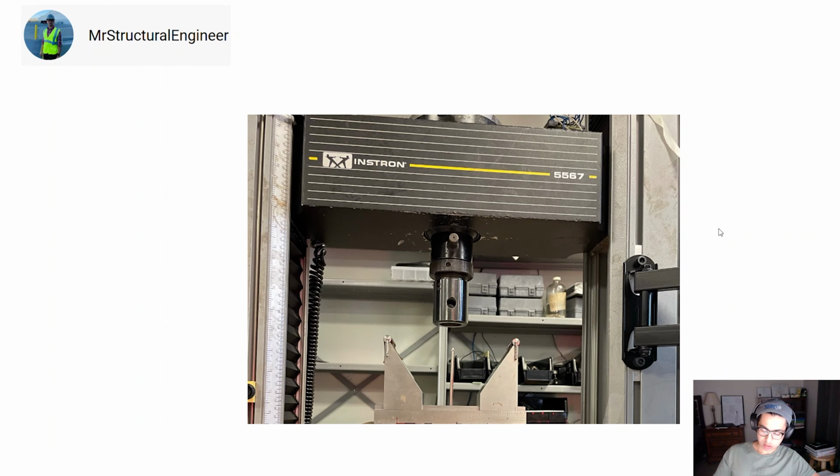The test was conducted using Instron 5567, and this is the 3-point bending fixture. Also, you can use a 3-point bending fixture or a 4-point bending fixture depending on the requirement. Also, please go back to ASTM again to see if the 3-point bending test is good for you.